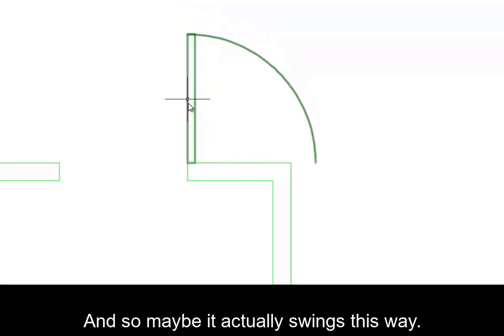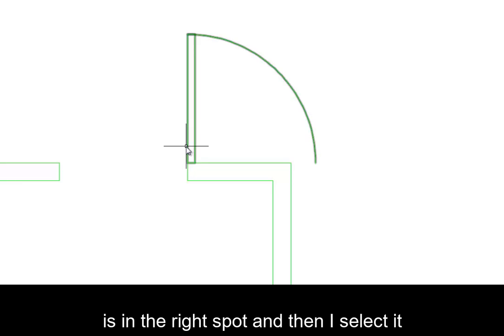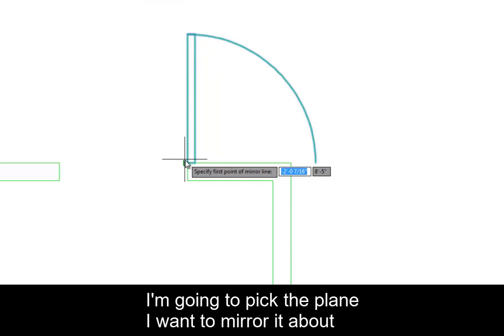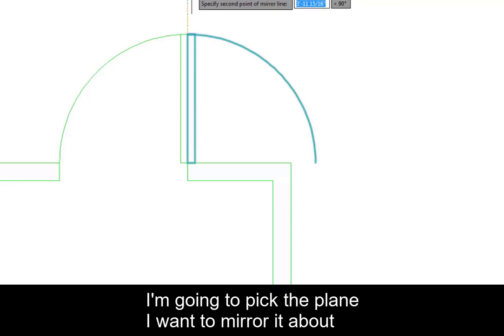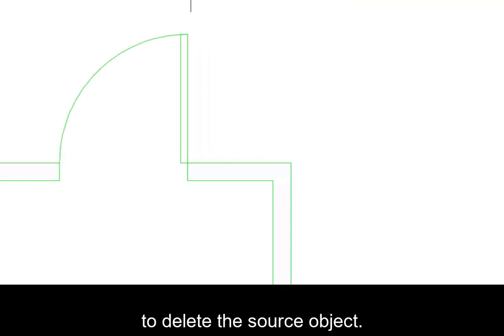And so maybe it actually swings this way. So I need to place it so that the hinge is in the right spot, and then I select it, and we'll use our mirror modify command. I'm going to pick the plane I want to mirror it about, and then we're going to hit Y and enter to delete the source object.